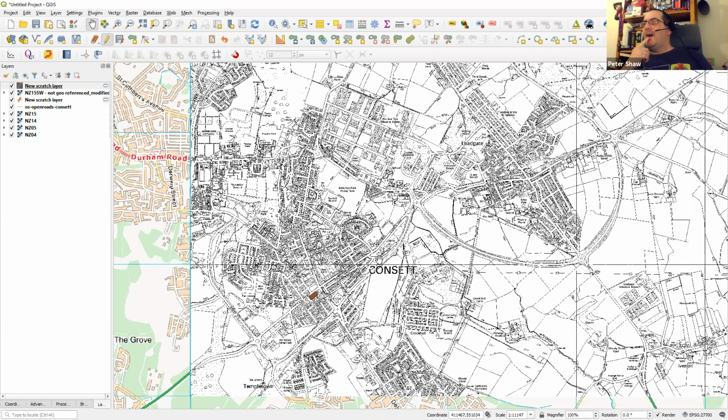Right. The Bering Strait is a long way off from Consett. So that suggests to me that it's recording WGS codes into the file. For the distance that it's off, Dave, if it had been sort of Consett but appearing down in the bottom corner of the UK, I would have said, well, okay, you probably just need to move your map a little bit, something like that. But for it to appear in the Bering Strait, that has to be a mismatched code somewhere.